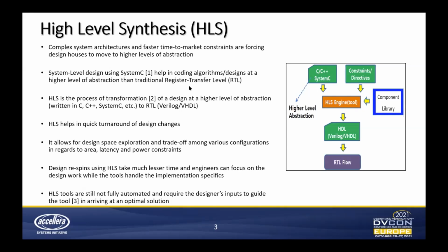Increasing complexity in system architecture and faster time to market constraints are forcing design houses to move to higher levels of abstraction. HLS EDA synthesis tools are more robust than before, and system level design using SystemC helps in coding algorithms or designs at a higher level of abstraction than the traditional RTL method.